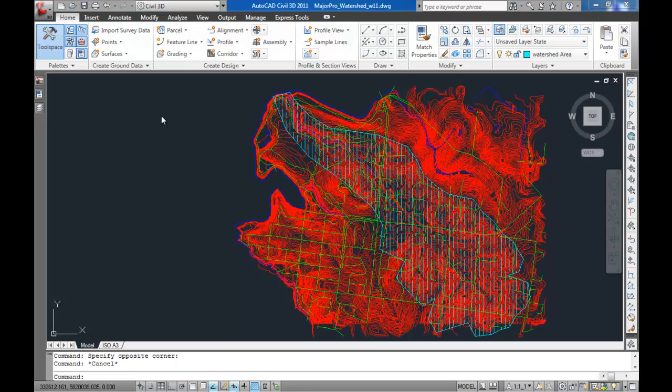And this week we're going to be looking at, I suppose, transferring all the information that we need onto a new document. We're going to be looking at selecting layers and colouring. We're going to be looking at the spine tool to actually map through all the different wetland areas that we need to work on, and we're going to be looking at viewports and also doing a 3D viewport.